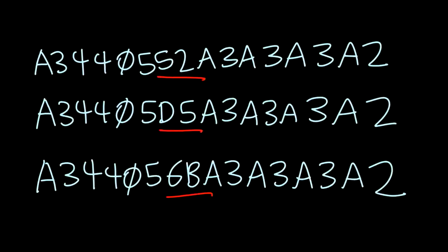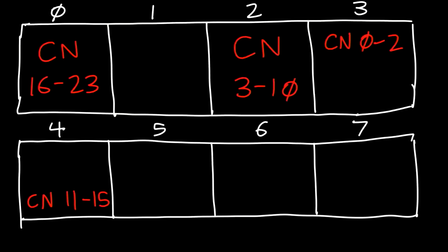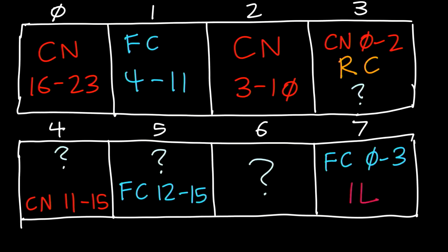So we do the same thing. We take a bunch of cards, we change some things, and notice the difference. Even longer later, and I'm not going to explain how, basically we can figure out what this actual data is. Again, there are 8 bytes. It turns out that the card number is splayed across all of these. For example, bits 0, 1, and 2 are in the 3rd byte, 3 to 10 are in the 2nd, and so forth. So all the card number bits are spread across those 8 bytes. Facility code is here, region code is here, issue level here, and stuff I don't know or care about.